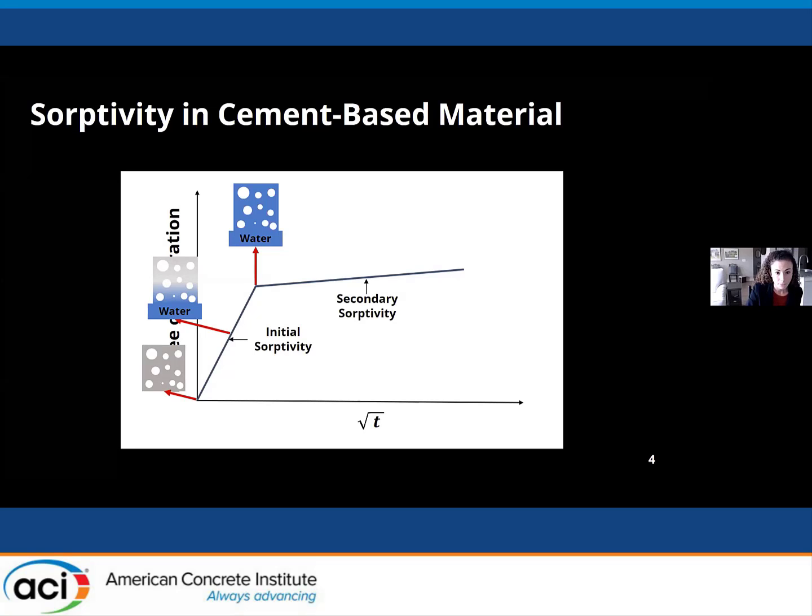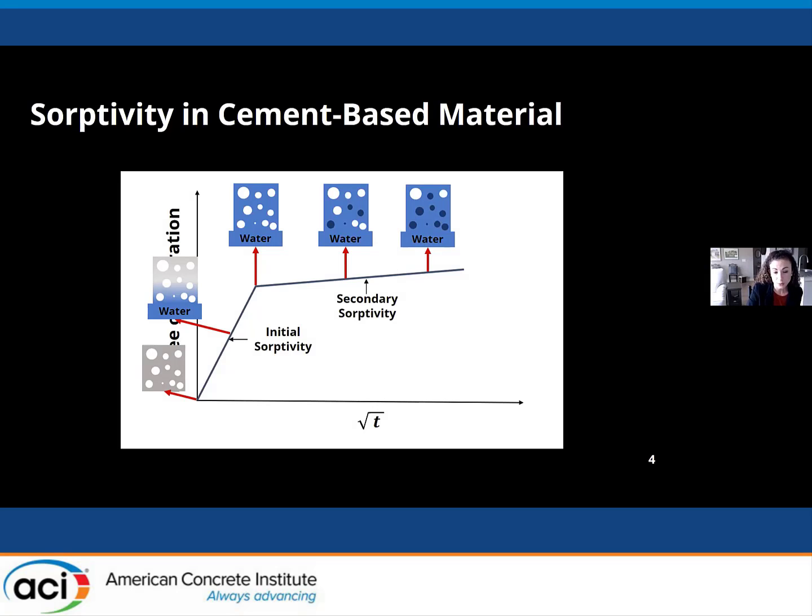water. And once the smaller pore system is filled with water, only then do we start to see the larger entrained and larger capillary voids start to fill with water. So that's really what I was just showing on the previous slide, is the larger pore system becoming saturated with time. And so the difference here is in our above ground infrastructure, the air or the pore space is always filled with air, but in these below ground systems, there's the potential for them to become saturated with greenhouse gases. So that's really what I was showing, and that CO2 is filling much faster than methane or